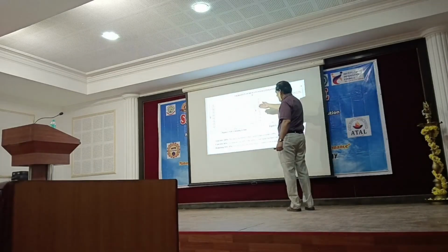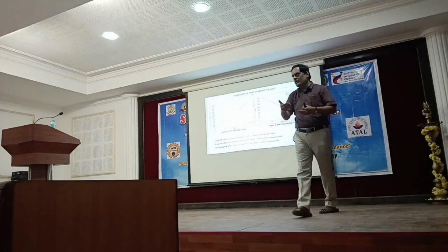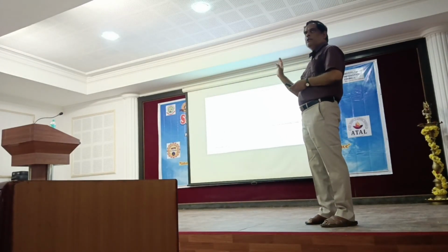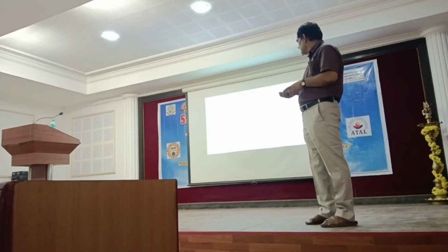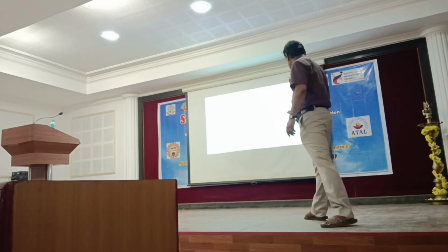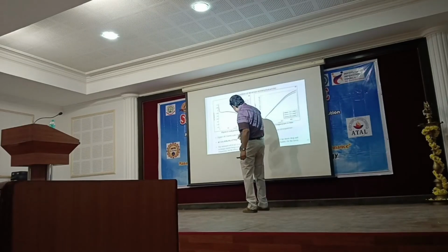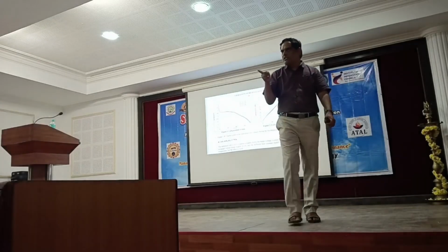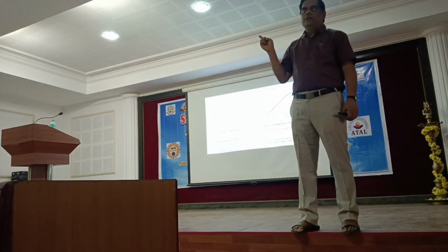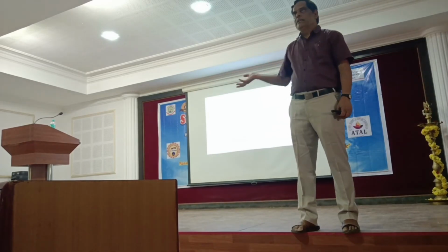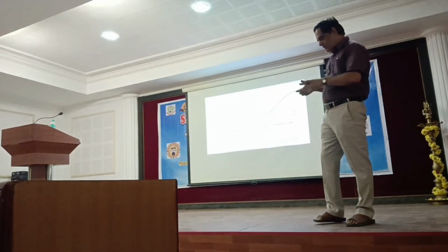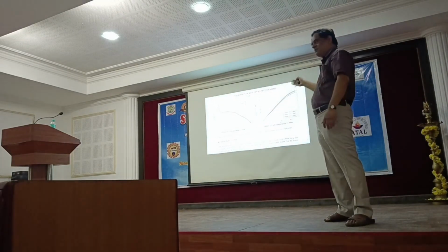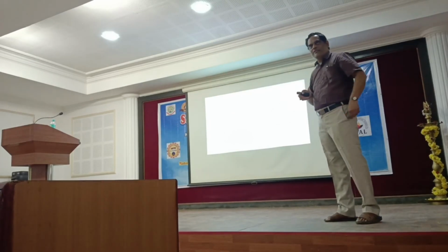Through COMSOL software, it is possible to get such figures. How much time does it take to reach 100% SOC during charging? And when I say discharging, how fast do you reach a depth of discharge of 5% or even 0%, and so on. Again, discuss what you see here. Cell potential versus time. I mentioned that at a very high C rate of charging or discharging, what will happen to voltage? It will decrease. I can simulate this. Having known the inputs for all the materials, by using the Butler-Volmer equation, I can also produce figures showing how the cell potential is going to diminish as a function of time.